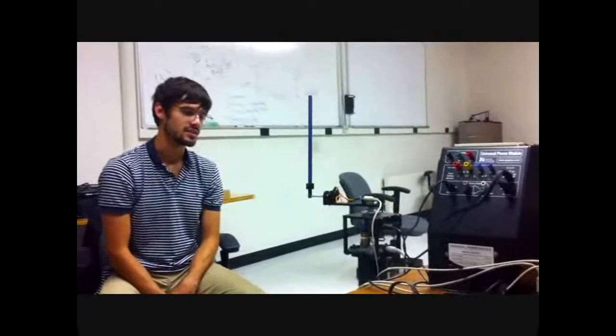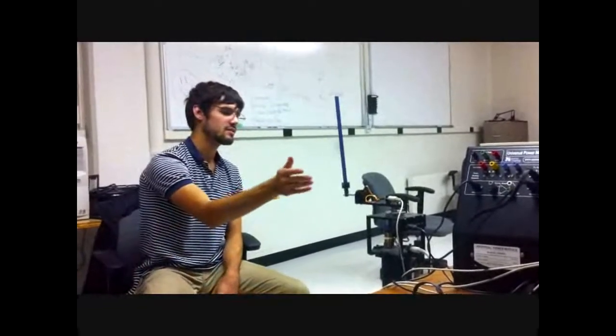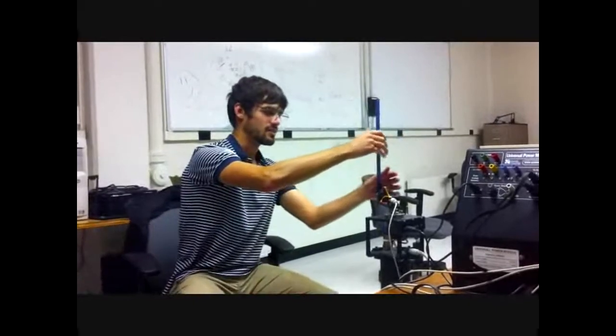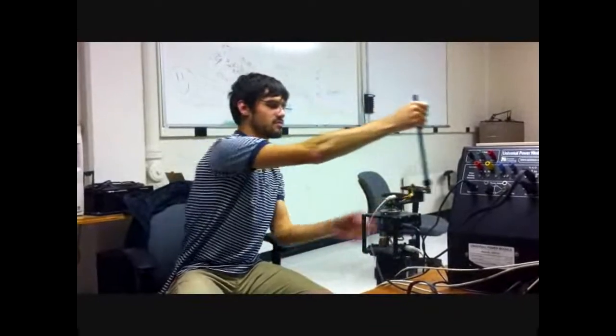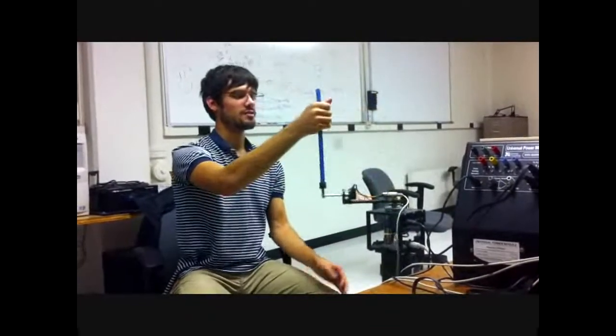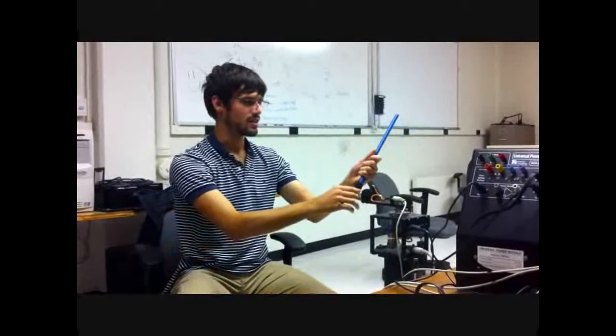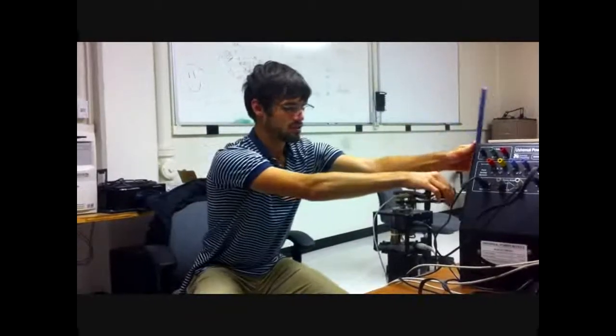Another thing we've done is make it so that, you can see how right now it accelerates so that the rotor gets under the pendulum so that the pendulum doesn't fall. And if we didn't turn that off, once it got to an angle like this, it would just spin in circles to try to get under it, even though it can't reach a velocity that's high enough to actually catch the pendulum, and that would hit things and hurt people and make people cry.